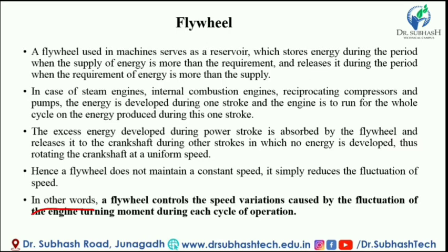In other words, the flywheel controls the speed variations caused by the fluctuation of engine turning moment during each cycle of operation.